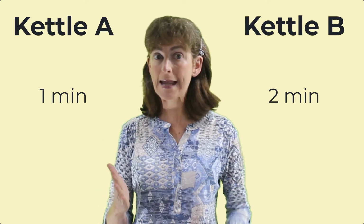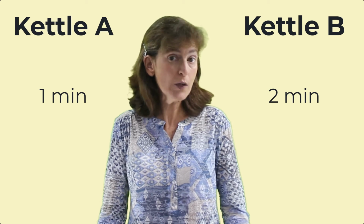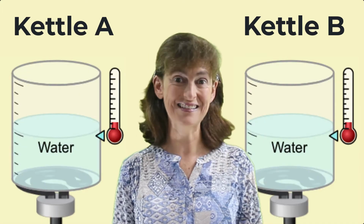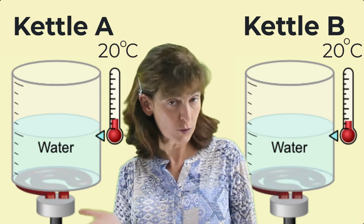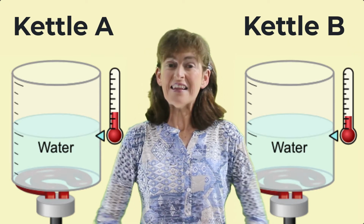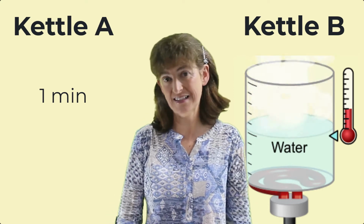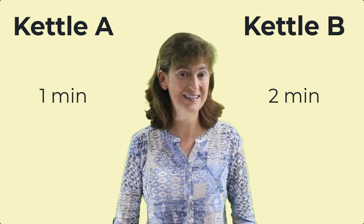First question, in which case is our energy consumption more, A or B or both the same, and why do you say that? We pay for energy consumption, so which one should we pay more for, A or B or both the same? Can you see that both kettles need to heat the same amount of water up, 1 liter, from the same starting temperature, 20 degrees Celsius, to the same ending temperature, 100 degrees Celsius? So can you see that they will both have to convert the same amount of electrical energy to heat energy because they're both doing the same job? So you should have to pay the same amount in both cases.